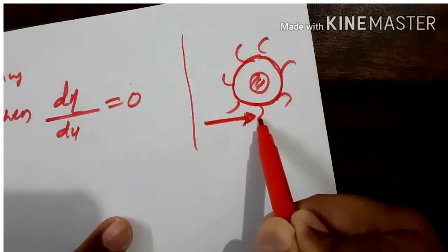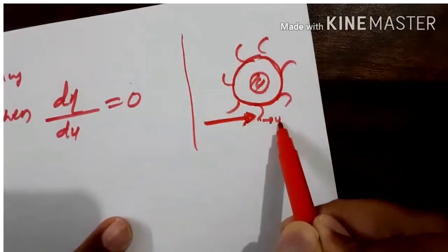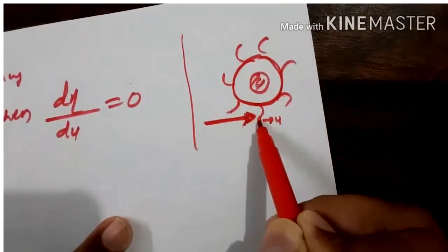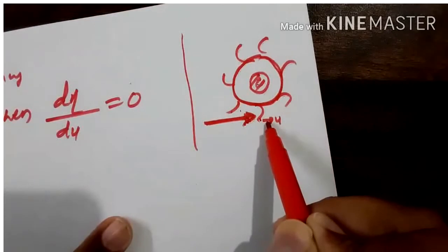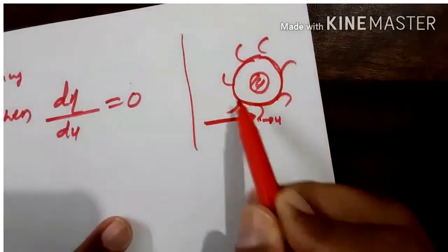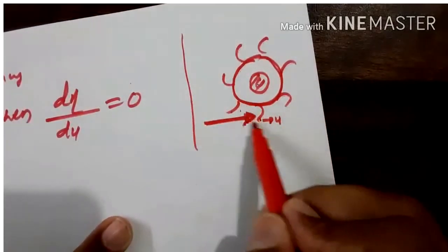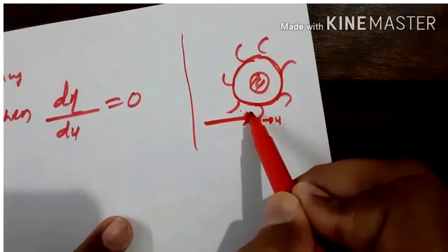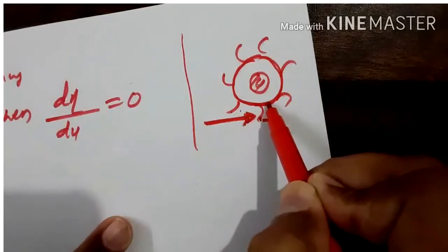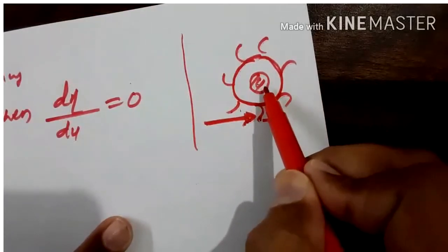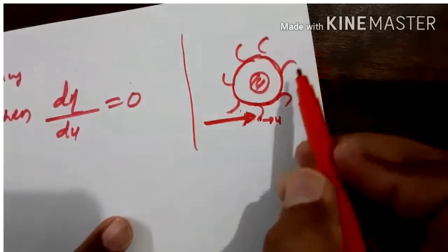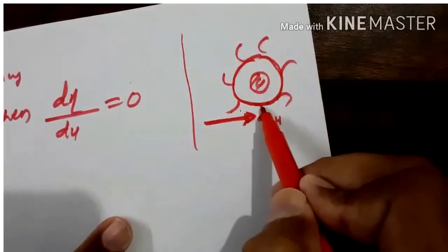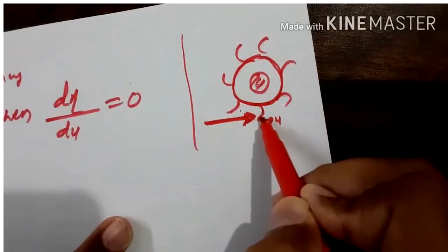Then this will be striking the blade, then the blade starts moving with a velocity u, it moves forward, then the next blade will come and stand before the jet, again that also receives a force, then that also moves, then again the next blade will come and stand before the jet. So this will continue. Then here the energy is being supplied from the blade to the impeller to the shaft to the generator. So the generation of electric power depends upon this blade velocity.